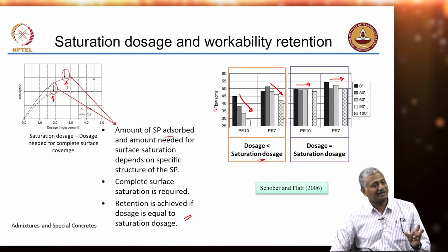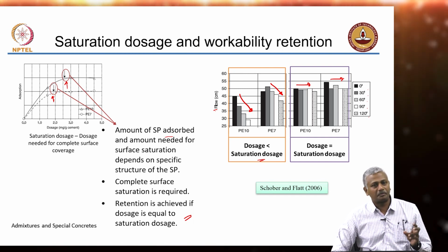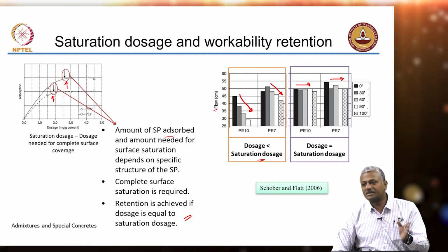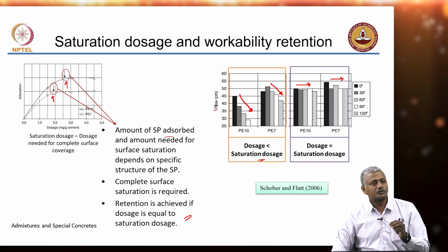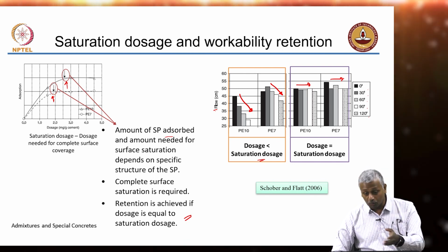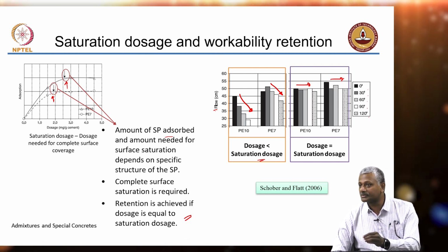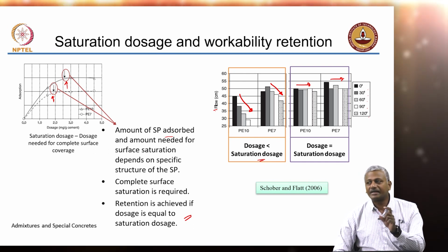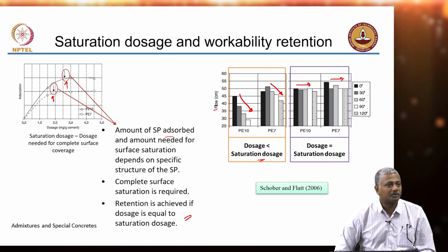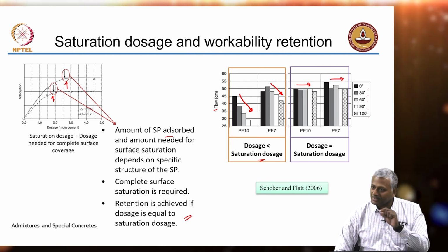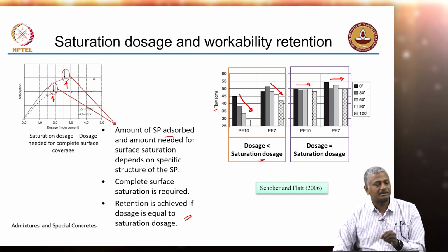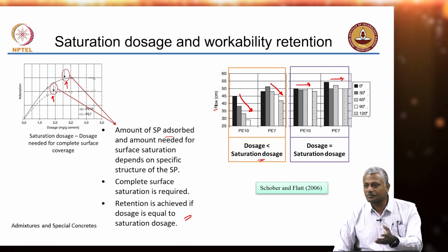Sometimes, without understanding how concrete should be designed for a particular project, people go with designs that they already have. As a result, they use combinations of materials, including the wrong choice of chemical admixtures and the wrong estimates of the water content required for the initial workability or workability retention. This is a problem that we have looked at in several sites. Now, how did this problem come about?